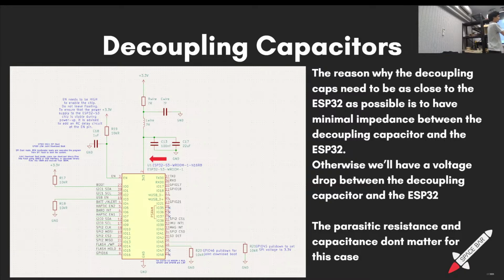Yes, so I've drawn it like this, but actually this 100 nanofarad is here, and the bulk decoupling capacitor is here. That one corresponds to that one. This is C7, this one. No, from the other example. This example? Yeah, can you match it? So which one corresponds to this? This is my huge bulk decoupling capacitor. It's this one. Then I've got a small one, which is this one. And then I would have one for each power pin like this.